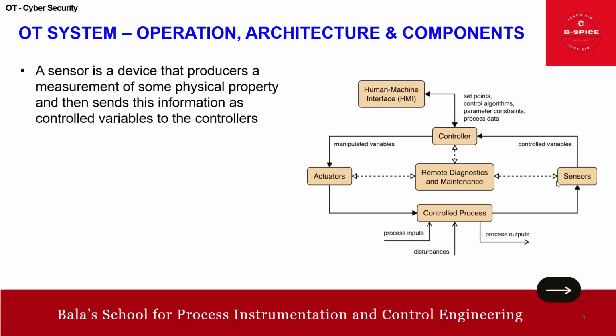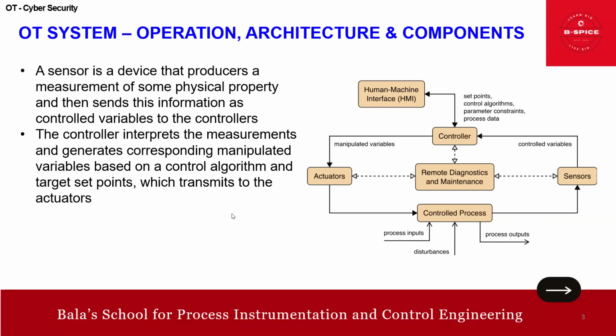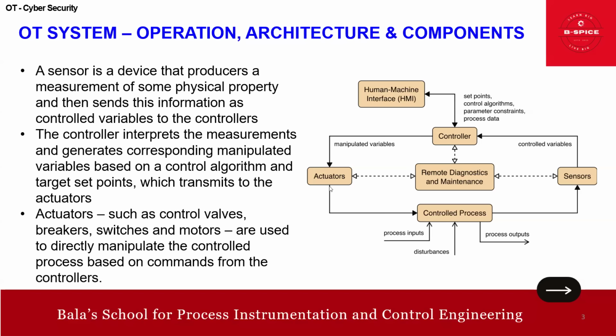A sensor is a device that produces a measurement of some physical property and then sends this information as a controlled variable to the controller. The controller interprets the measurements and generates corresponding manipulated variables based on the algorithm and target set point, which it transmits to the actuator. Actuators such as control valves, breakers, switches, and motors are used to directly manipulate the control process based on the commands from the controller.